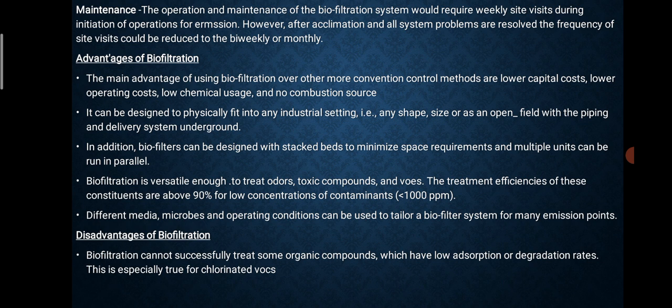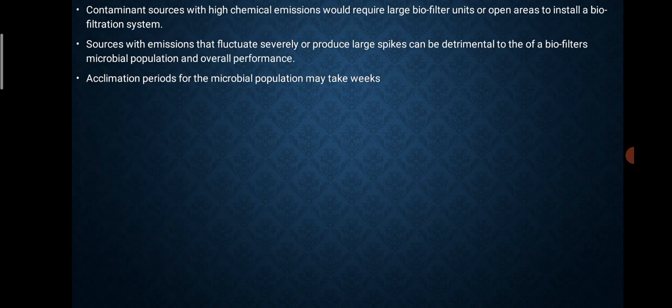Disadvantages of biofiltration: biofiltration cannot successfully treat some organic components which have low adsorption or degradation rates. This is especially true for chlorinated volatile organic compounds. Contaminant sources with high chemical emission would require large biofilter units or open area to install biofiltration system.